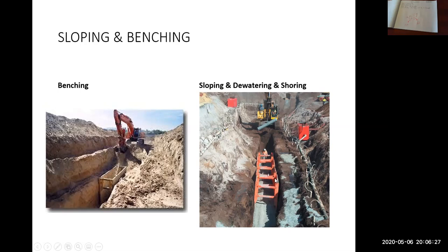What that does is it dries out the groundwater that's in the trench. These systems are quite effective, but they're very costly. They're typically called well points. There's a system on either side of the trench, so it runs the full length of the trench. It looks like it even maybe turns the corner there.